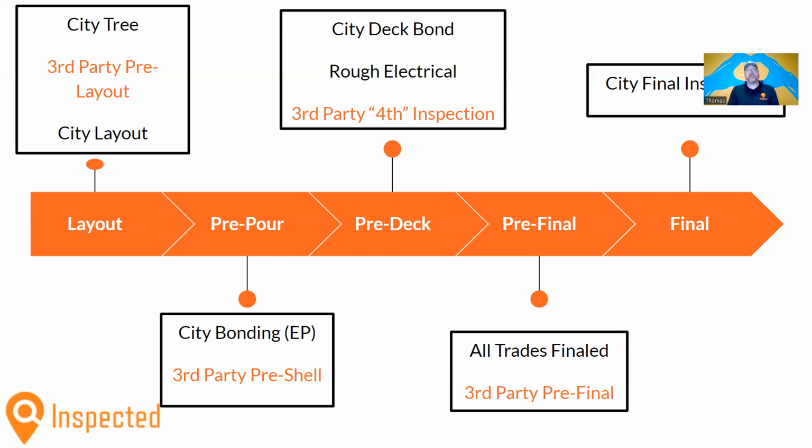If the pool is being built concurrently with a house, it is often the case where the builder will manifold the pipes next to the pool, and then at a later date, dig the equipment trench and put the equipment and pipes in their designed location. If that is the case, please take pictures of the equipment trench so that we know you have preserved the pipe diameter and quantity from the pool all the way to the equipment set.